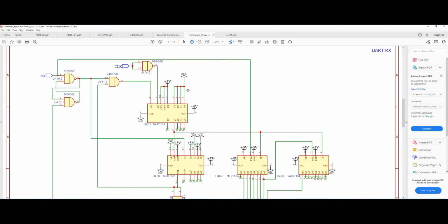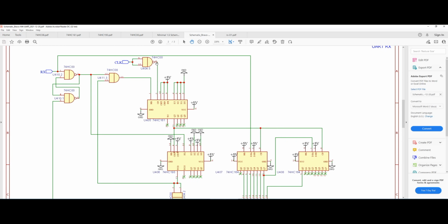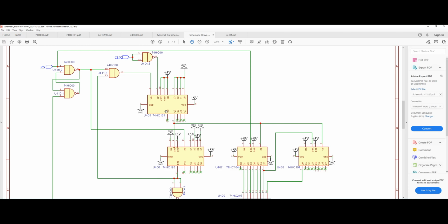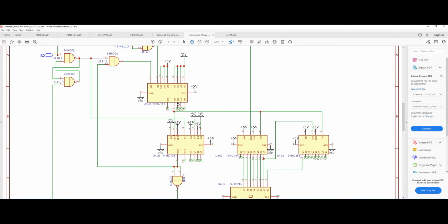So when the clocks come into our clock divider, again, just like the previous circuit, we are not inputting anything from the input side. We are really just pulsing this chip to count. And what we get in the output of this chip, which is the most significant bit, is 1/16 of the clock rate that is coming into the chip. So this is just a clock divider, takes the original clock, divides it by 16, and outputs it on pin number 11.